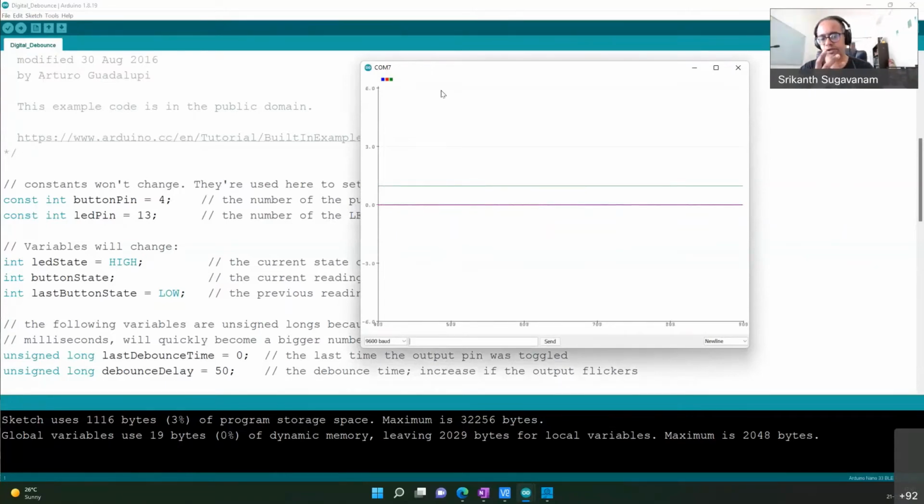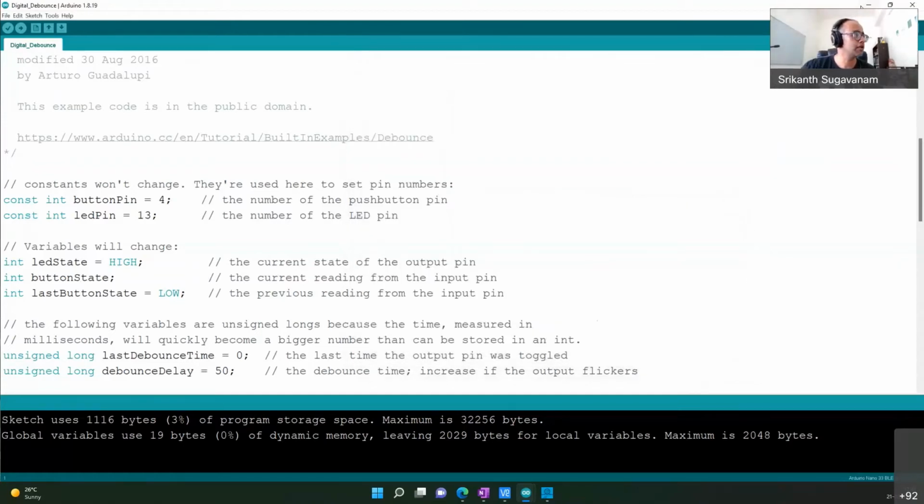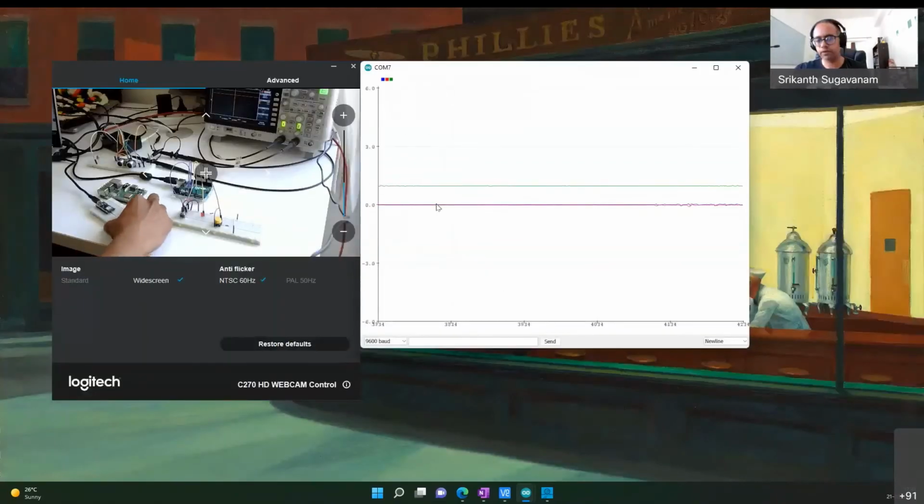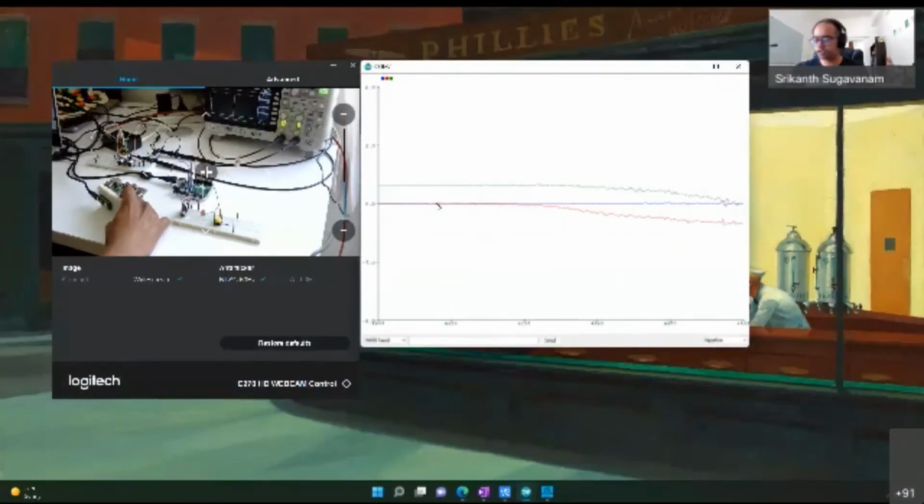You've got three axes on an accelerometer: the x-axis, the y-axis, and the z-axis. All right. You see this green line? This green line is actually at a value of 1. The value of 1 means that particular axis is subject to an acceleration of g, which is 9.8 meters per second squared. All right. So now, if I rotate my accelerometer, let me show it in this way. Now let me rotate my device. All right. See how the curves changed. Now a different axis is now subject to the gravitational pull. Okay. Let me again rotate it.